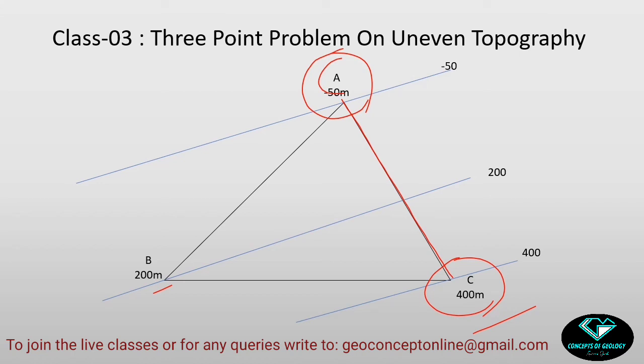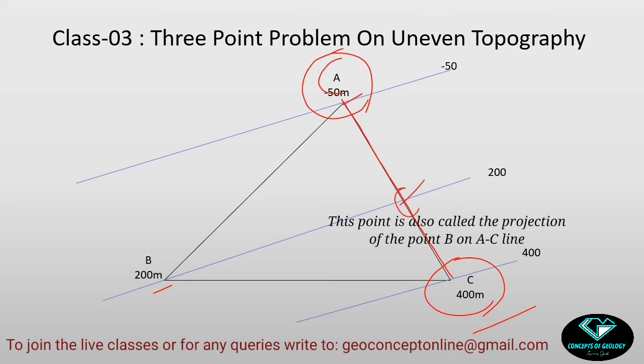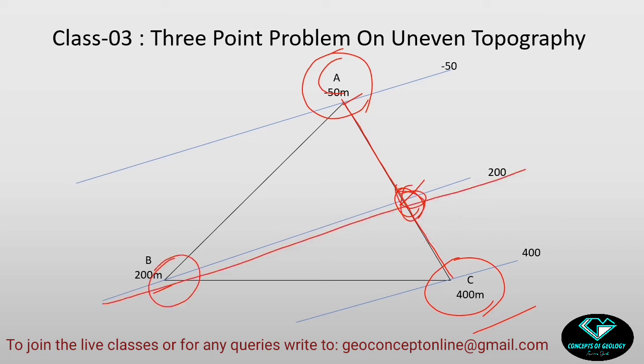The distance I have copied by means of a divider, so I will put one end of the divider here, and I will try to find out where the other end will be pointing. Suppose it is pointing here, so that means this is the point where I will get the 200 meter RL value for the coal seam. So if I join this 200 and this 200 with a line, this will be the 200 meter strike line or 200 meter stratum contour.